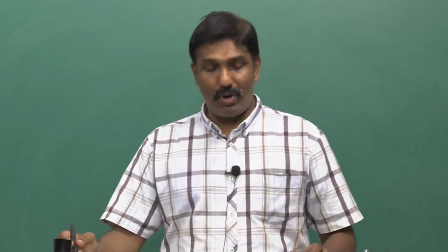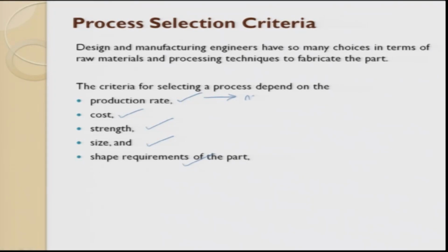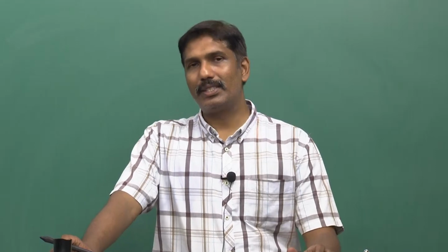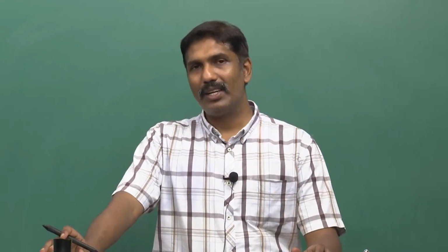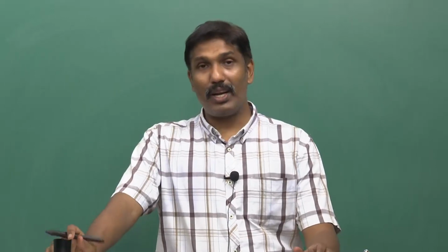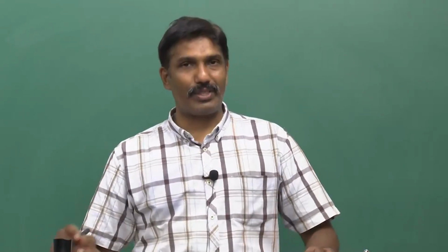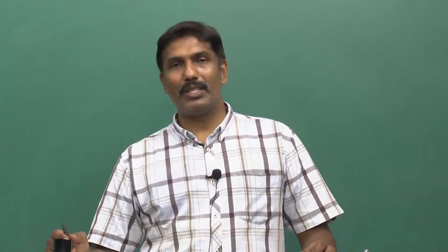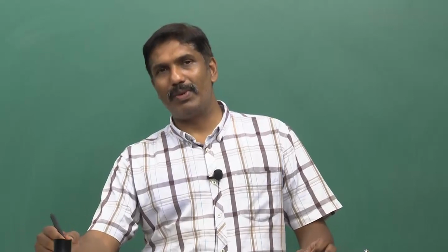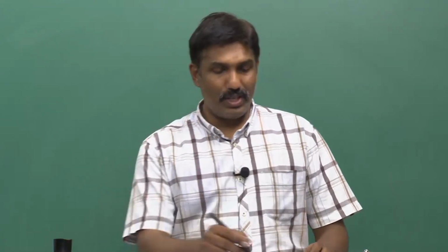Production rate is important because here we talk about the number of parts to be produced. For example, if you invest in the injection molding process, the production rate should be enormously high, such that the investment for die fabrication can be recovered. So, production rate plays a very important role, and then the economics. What is the price which a customer will be ready to afford for this part? So, this is the costing.